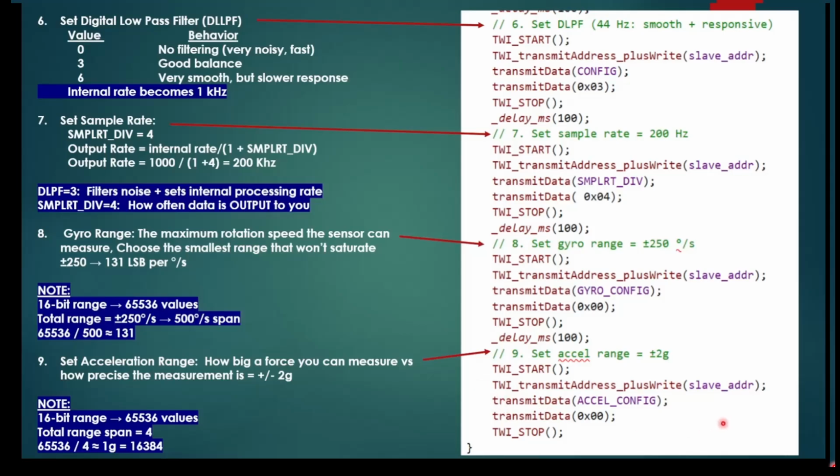So we do the acceleration configuration, we set to 0. So that gives you all the configuration we have to do for this unit. Basically we set up ranges, we set up the rates, and then decided not to use the FIFO. We had to wake up the unit, and we have to enable an instrument. So with that, let's go back to our presentation.